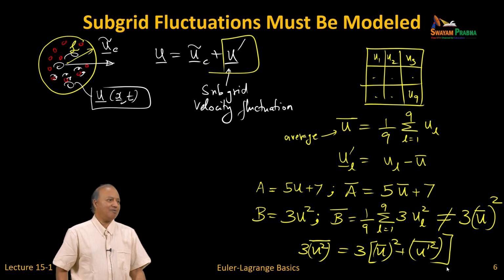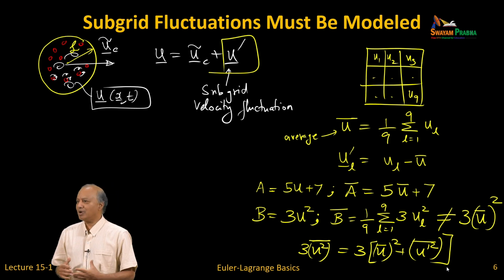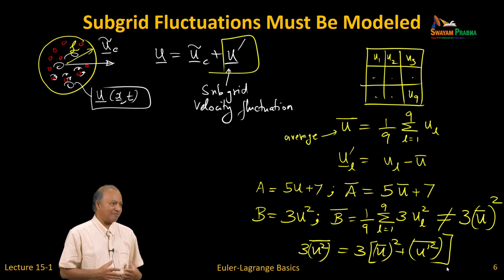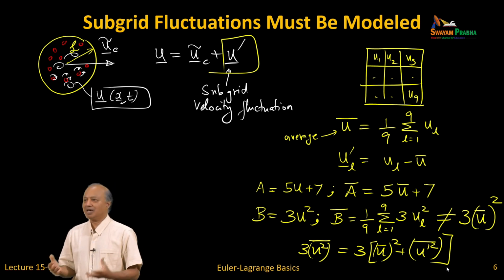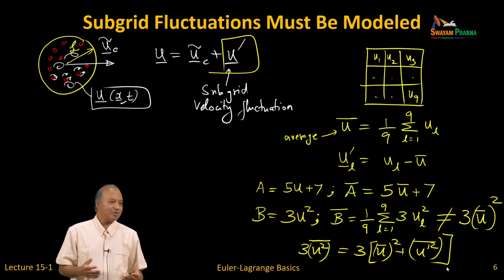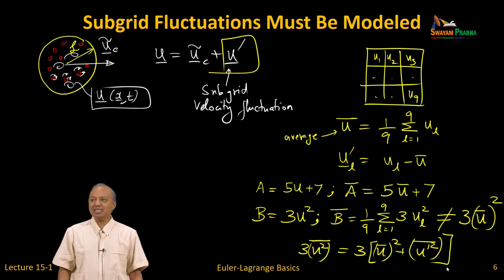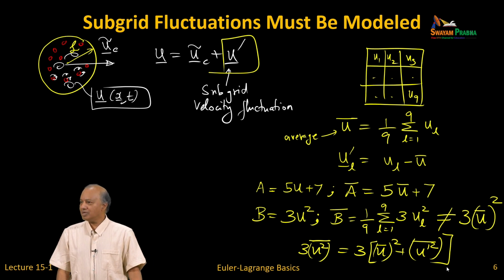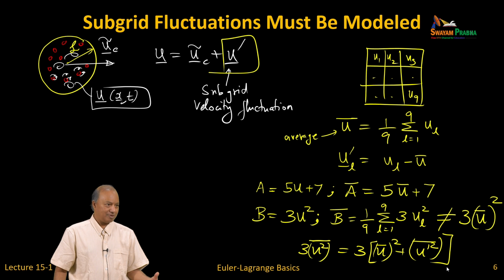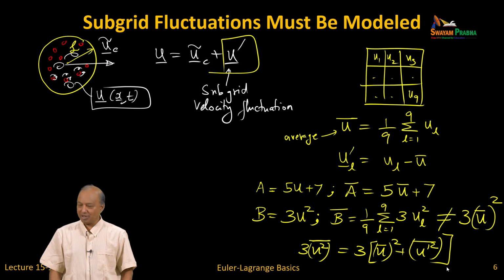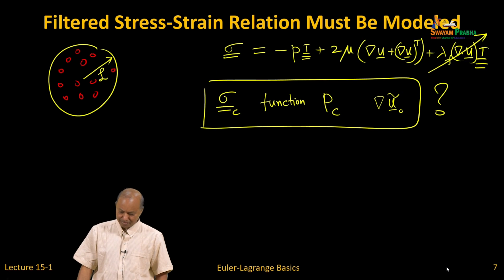But right now I am saying just generally what is happening is sub-grid fluctuations in the fluid themselves, temperature fluctuation, velocity fluctuation, pressure fluctuations, etc., will matter, and they will give rise to what are called Reynolds stress like terms. Okay. You have to model them. Okay. If they are important, they need to be modeled.